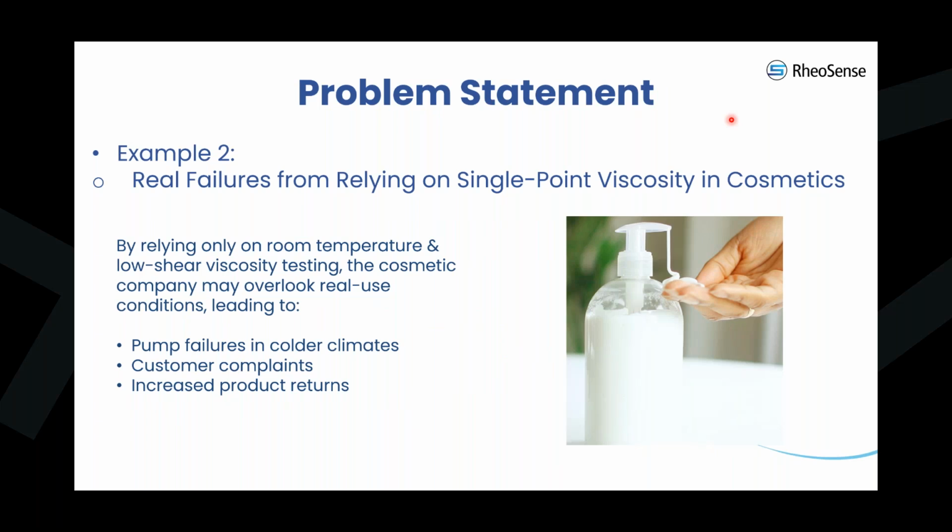Why did this happen? Because the company only looked at viscosity under one condition and didn't evaluate how it would behave across a range of temperatures or during actual use. When the lotion is squeezed or pumped, it can experience higher shear rates. As a result, customers complained and product returns increased. So the key takeaway here is simple. Ignoring how viscosity changes with temperature and shear rate can lead to poor user experience and costly product failure.